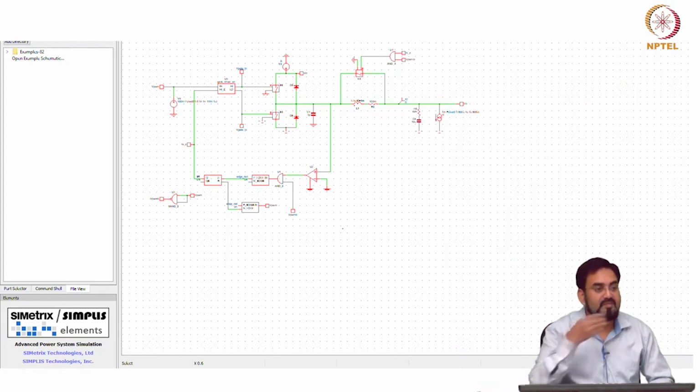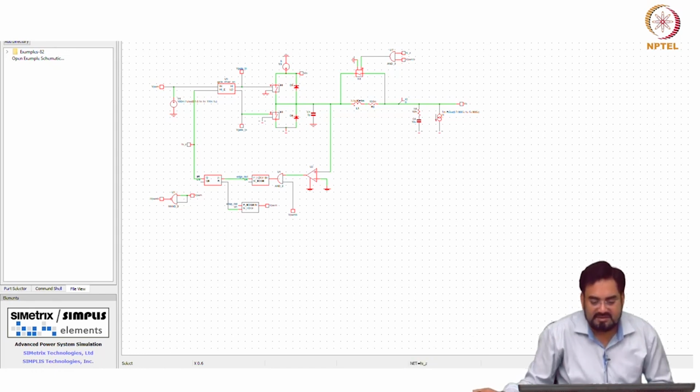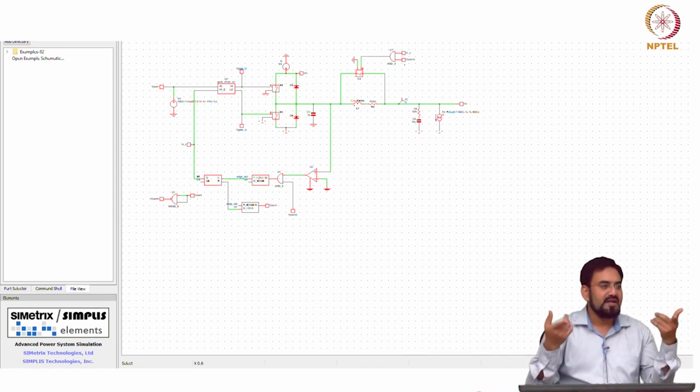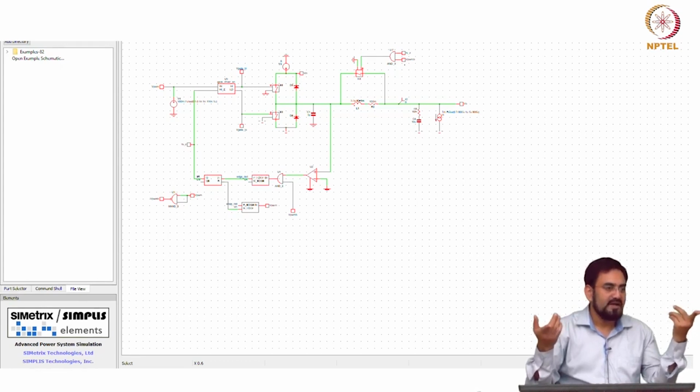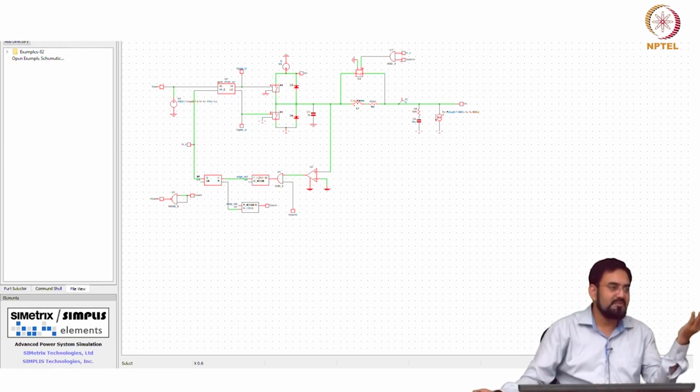How do you implement that logic with the freewheeling? Which logic? No, this is during high Z and PWM. So, we know when PWM is low and high Z is also high, that is why I am using PWM bar here actually, which means PWM is low means PWM bar is high and high Z is high, both are high, 1 and it will force this to turn on, that is it.